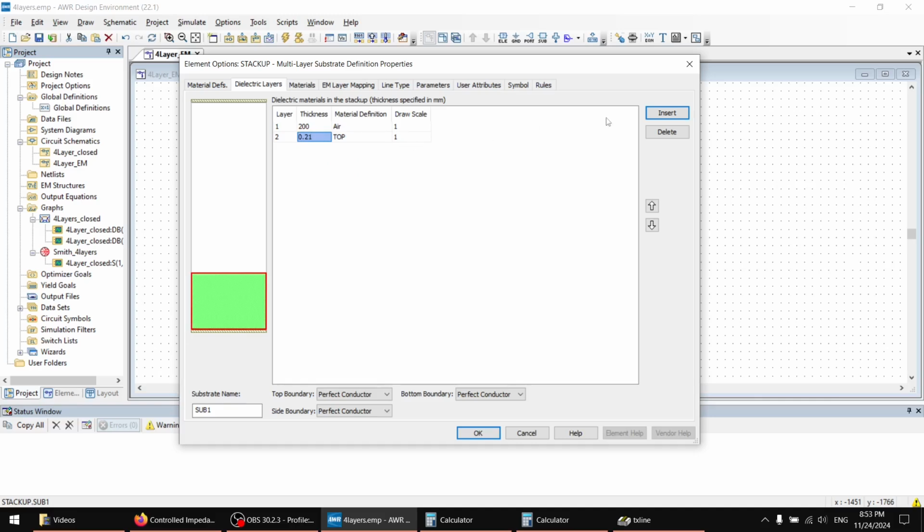Now the scale, I will not care that much about the scale, because you will notice that these blocks will be the same height, even if I change it to 1.065. And this is our FR4 core. So you can see it changed the color. It has 4.6 dielectric constant, and it has 4.4 and 0.2 for a prepreg.